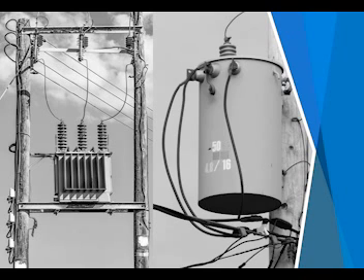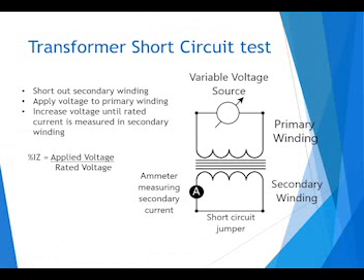However, the limitation that we have is whatever the kVA rating on our primary or our input to our transformer is going to be exactly the same kVA rating that we're going to have on our output as well. Since this number is related, we can also apply this to our theory based on our transformer understanding. In order to figure out what my interrupt rating is going to be, the first thing I need to do is find out what the percent IZ rating is, which is the impedance rating inside the transformer. And to do this, I do a transformer short circuit test.